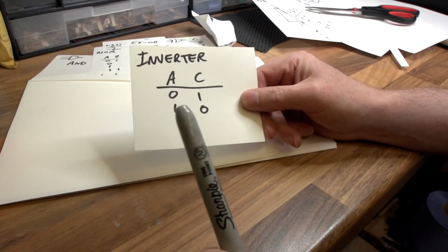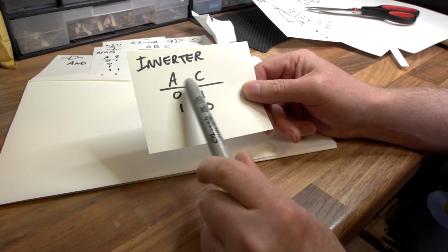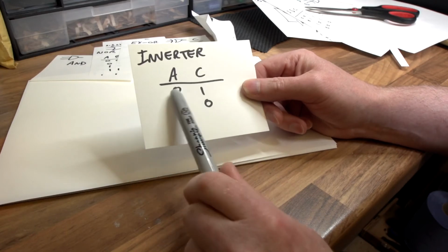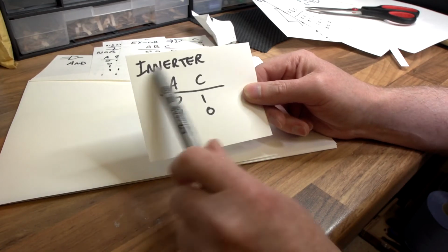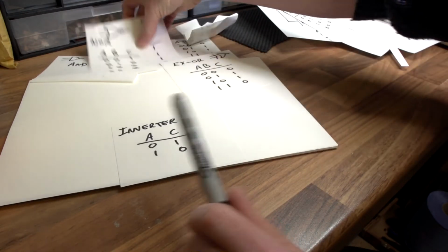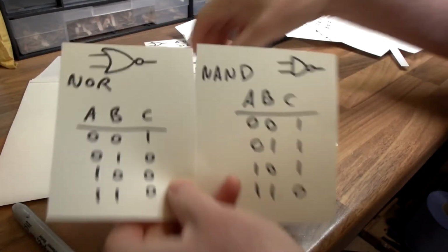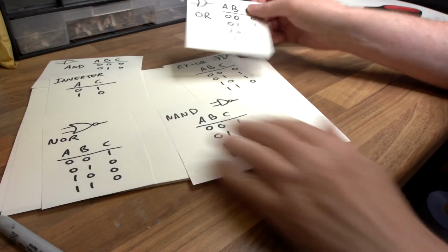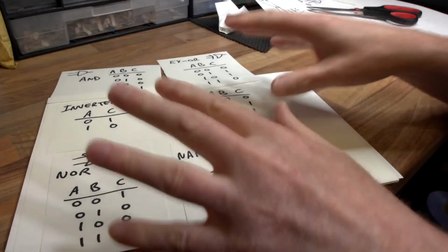The most basic of gates is probably the inverter, where you've only got 1 input, you don't have a B anymore, and you've got the output pin, which I've just called C. And basically whatever you put in, it's the opposite. 0 in, you get a 1 out, 1 in, you get a 0 out. And it's this inverter functionality that we see on the output of NAND gates and NOR gates, where you have a circle on the output. That's basically what the inverter's doing. And that's really the truth tables for all the major gates. That's all the 6 major gates. Everything pretty much revolves around those.